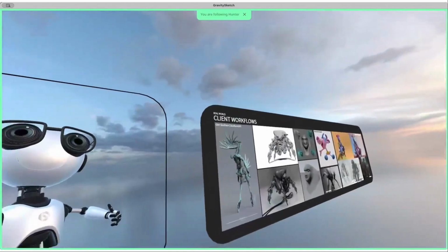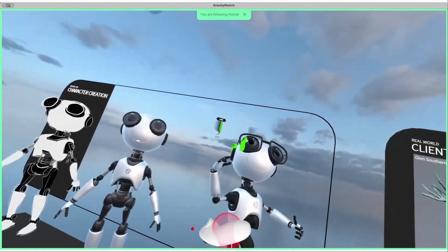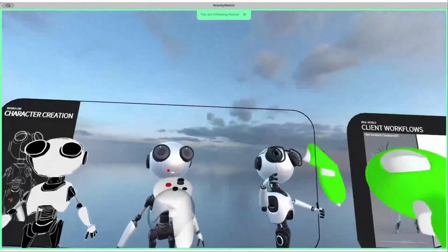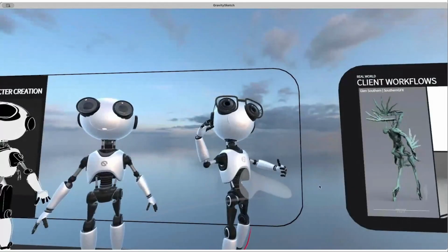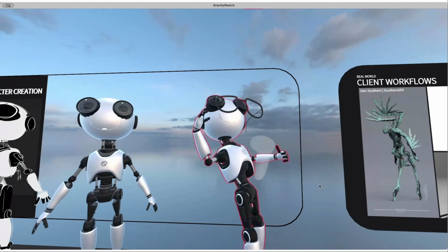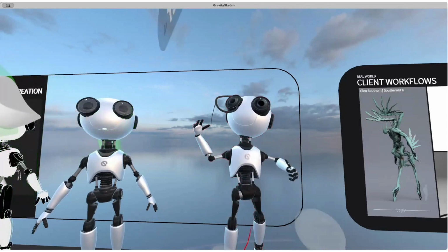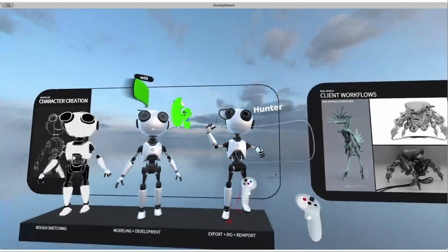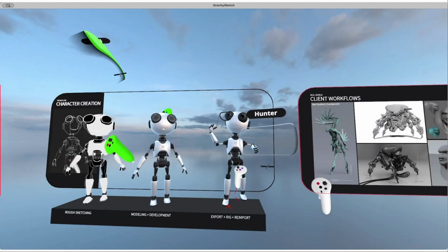And then in terms of the question on UV unwrapping, in this case, I took this file and sent it over to Blender, and I have this all as one object that I then UV unwrapped in Blender and applied these materials to. So while this is one object, the materials here are actually their own texture map that I brought in. I'm not sure if I have that on hand, but I can certainly look really quick to show you an example of what that looks like, because, yeah, here it is.